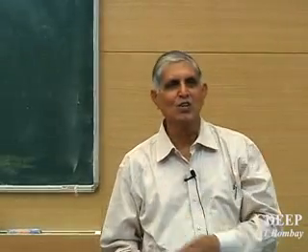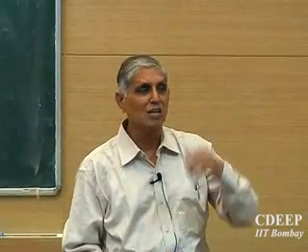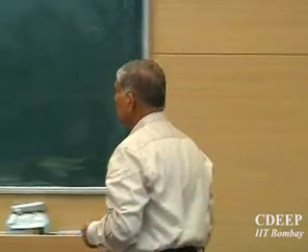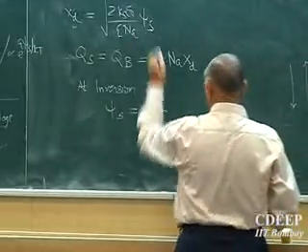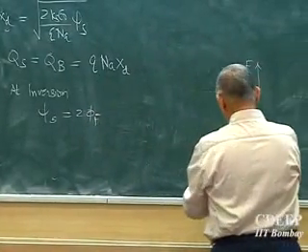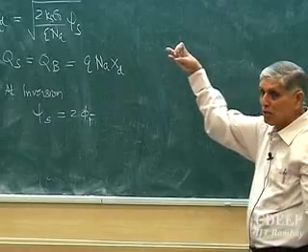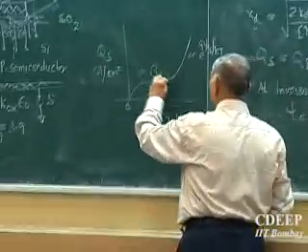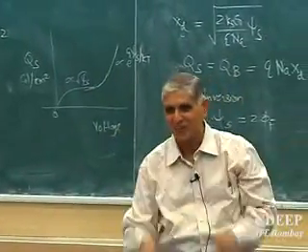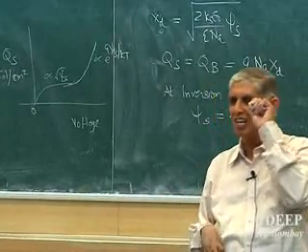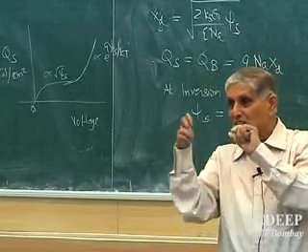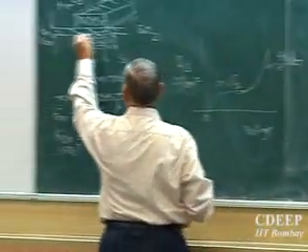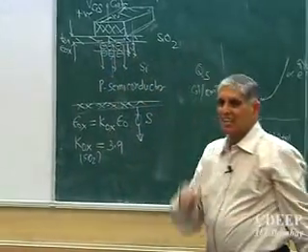But at psi s equal to 2 phi f and above, we have a large number of electrons available, and we say now it is in inversion. So the definition we say, at inversion psi s is 2 phi f. This is slightly catchy, though it should be only phi f, but we still say it is 2 phi f. The reason is this: somewhere in this region both of them are contributing. Some small change in the depletion layer is still seen, so it is not that only free electrons are coming, slight change is seen here also.